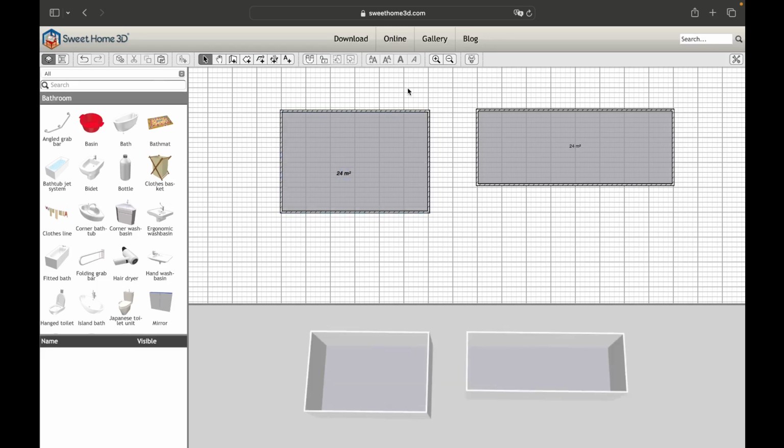As regards the dimensions of our room, we use the Create Dimensions tool. We select the command and with the left mouse button click on the external corner of a wall. Now we move the mouse along the side that we want to measure, and at the end of it, we click again with the left button. As a third and final step, we decide the distance from the building and click to establish it. In this case, we have created an external dimension, but it is possible to create an internal one using the internal corners of the wall as the extremes of the dimension, like this.